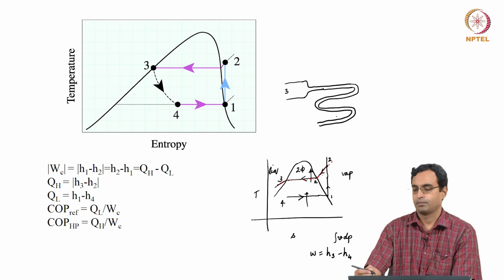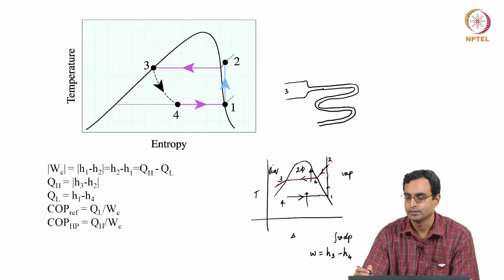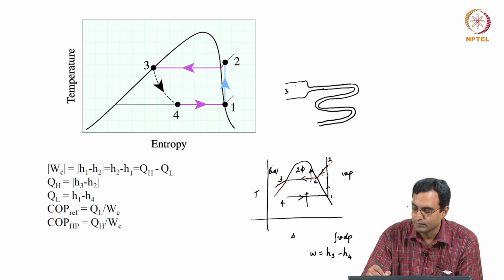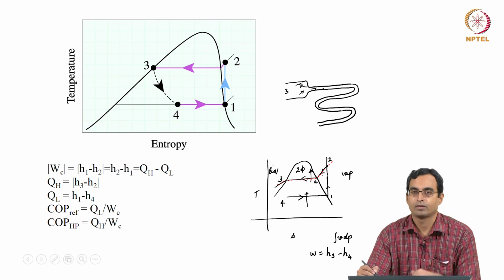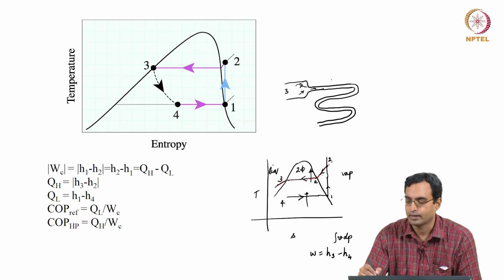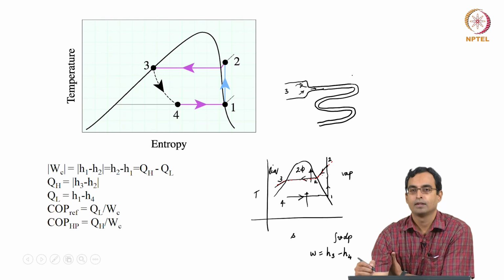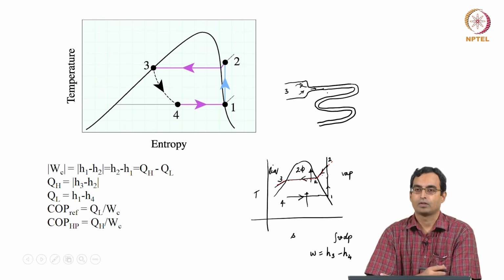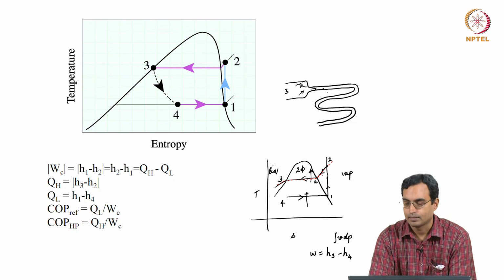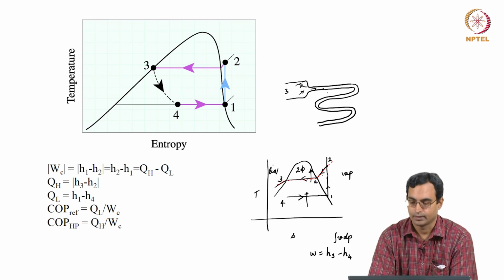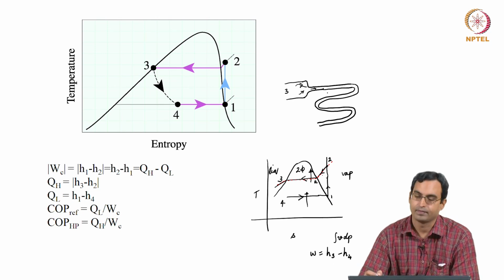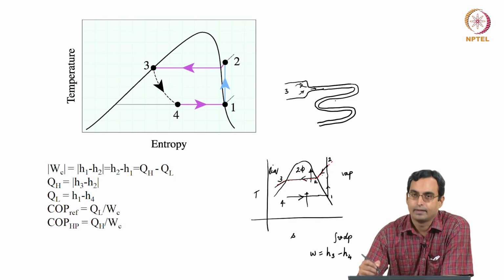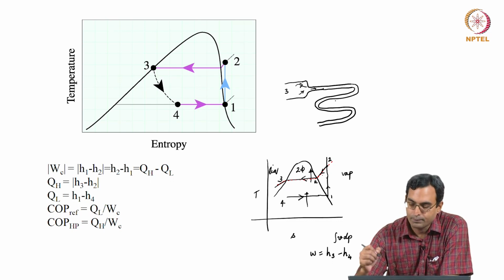Of course, you would possibly have the same diameter. I have not drawn it all that well, but what we see is when this liquid flows in through this tube, it has viscosity. So, it has a lot of pressure drop. So, the pressure drops in this case. If this flows fast, we can assume that this process happens adiabatically. So, it is adiabatic, but the pressure is dropping, and in this process what we see is that the enthalpy remains constant. If we assume this to be steady state and if we ignore changes in potential and kinetic energy, then the enthalpy remains constant and the pressure drops.